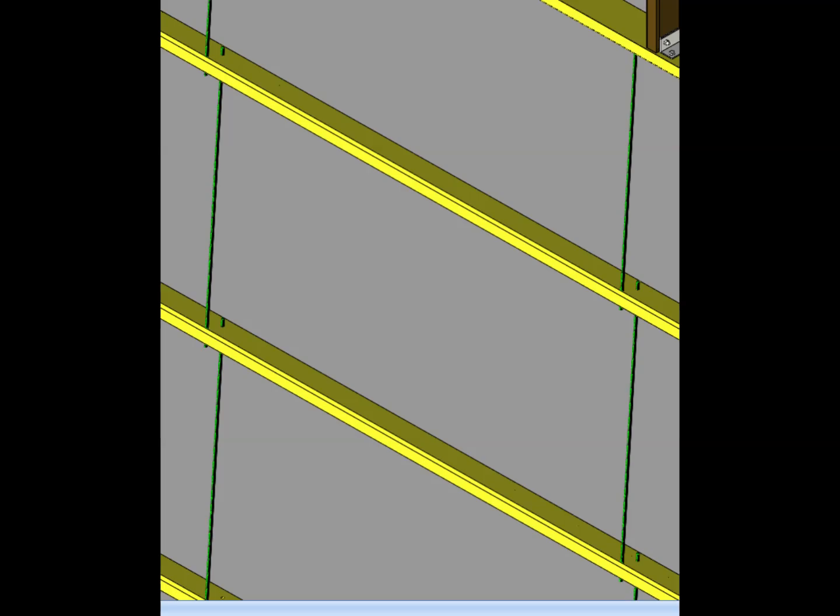Now focus again on the close-up. The horizontal yellow members provide the visible framing lines of the side wall, while the green sag rods are much thinner and therefore can easily be missed when viewing the complete structure. This is exactly why a close 3D view is useful for learning PEB detailing. It allows us to isolate one particular structural component and understand its position without the visual distraction of the complete building.